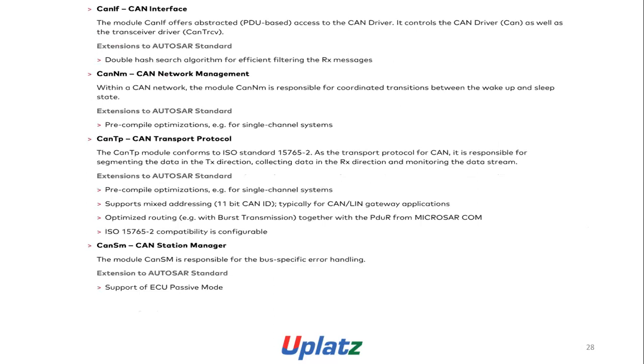The module CAN IF offers abstracted hardware-based access to the CAN driver. It controls the CAN driver, CAN, as well as the transceiver driver, CAN TRCV, according to the AUTOSAR standard. Extension to the AUTOSAR standard: an algorithm for efficient filtering of the RX messages.